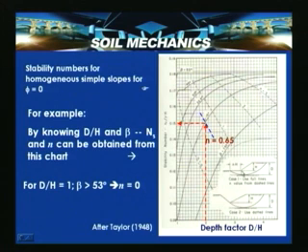If n is equal to 0, it passes through the toe of the slope. That is a case which actually arises where d by h is equal to 1. That means that beyond beta greater than 53, it passes through the toe of the slope. And this is case 2, use the dotted lines which are shown here. These are the lines which should be used for reading these slides.